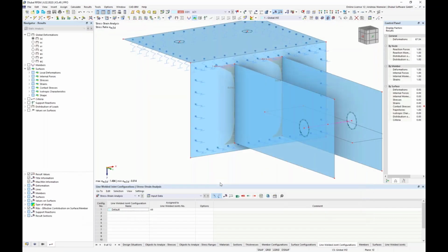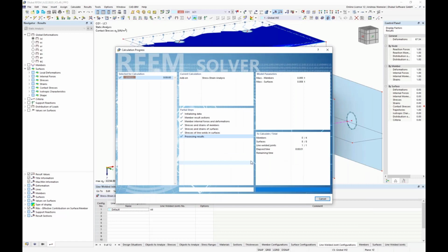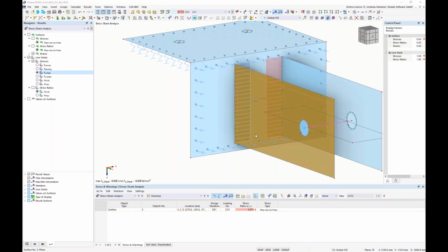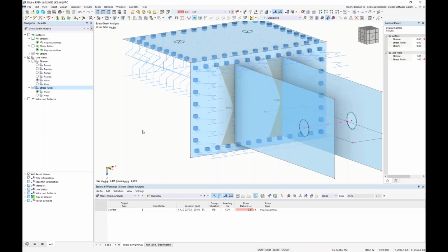And if you check this and recalculate the stress-strain result, you will now get a suitable result, because the shear load is now constant. And the normal load will be distributed linearly, and this results in a better utilization, and you can do the check. But it really depends on which stresses you use, whether smoothed or not smoothed.